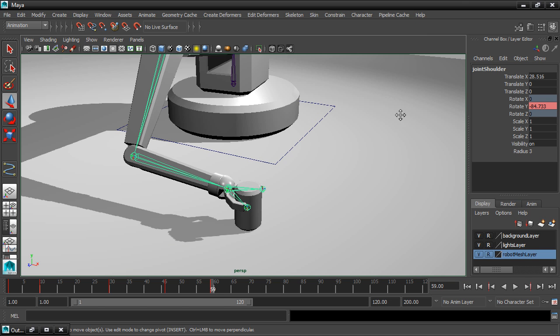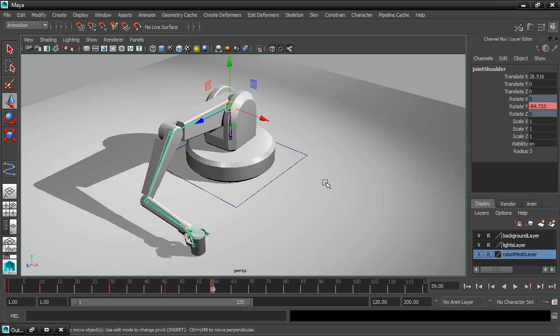Cool. So at this point now we can think about how we're going to connect the object to the rig. And that can be done with the parent constraint as well. And in fact, we can parent constrain to multiple objects and transfer those links over time. This is an advantage that parent constraints have over standard links.